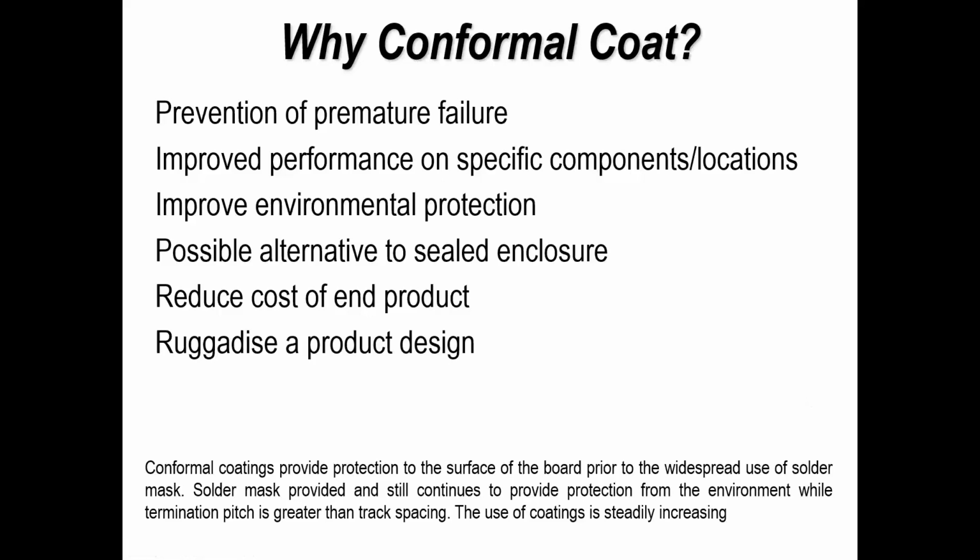So first of all, why do we want conformal coating? Well, it potentially prevents premature failure of product. If a product is going to be operating in a condensing environment, something where moisture can evaporate and condense onto the subject, then having some sort of protection coating is beneficial. If a product is being operated in an environment where you've got toxic chemicals, other gaseous forms of corrosive products, then some conformal coatings, again, may be beneficial to you.